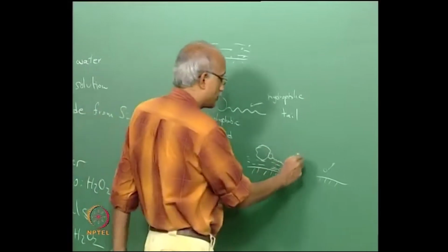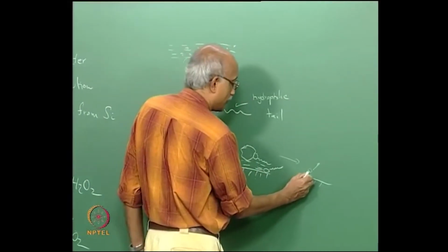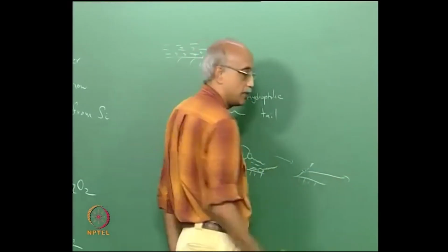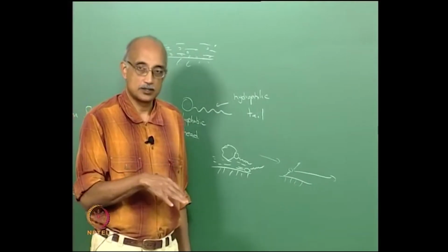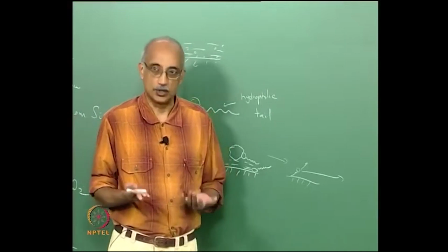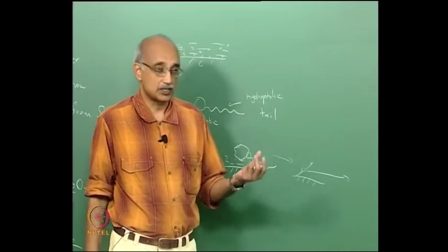Now if you have some kind of a flow mechanism that's also set up, these particles that move away from the surface and get into the bulk of the liquid can quickly be transported away from the surface so that they don't re-entrain or redeposit on the surface. So that's basically how surfactant based cleaning works. Very simple. It's mostly a physical action.